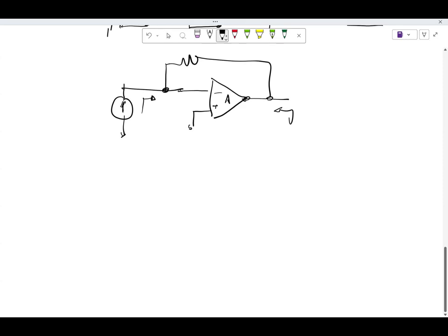So if you have this configuration, or if I draw it like this, assume the transistor is in saturation and infinite r0 and all those things. Incrementally, the output impedance is infinite. From here, if gm is infinite, this is 0, right? Tends to, I should write, tends to. So this is kind of a current buffer.